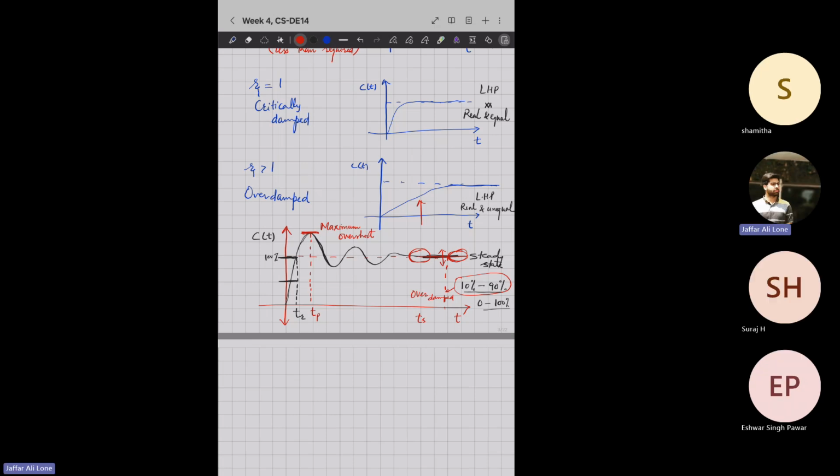But if that is not the case, if you want accuracy and do not want overshoot, you will accept a higher rise time, since I don't want overshoot. You will go with the overdamped setting. See, there is no overshoot. So it depends. We will see in the later part of this lecture that we use controllers.